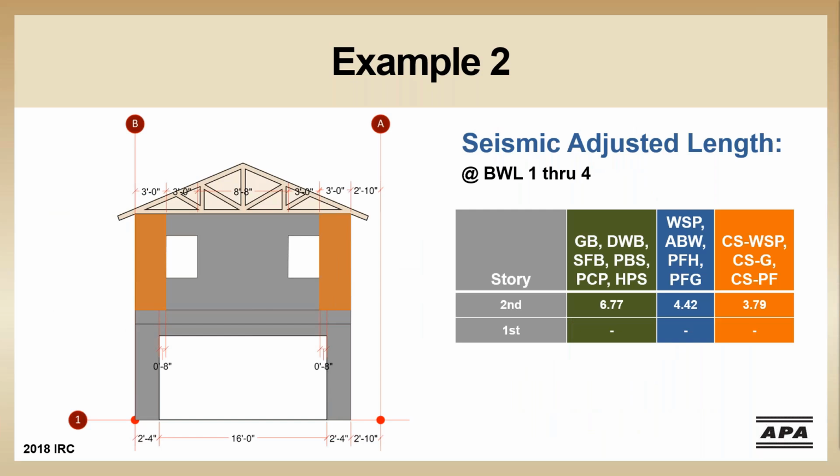Remember from the irregularity check that we can only overhang an opening by 1 foot. So that nice 8-foot, 8-inch wall section at the second floor, we can't use the entire length. That's right here. That leaves us 2 3-foot sections of wall. That first set of 6 types can be ruled out immediately, since all 6 require a minimum length of 48 inches before the braced wall panel counts towards our total.